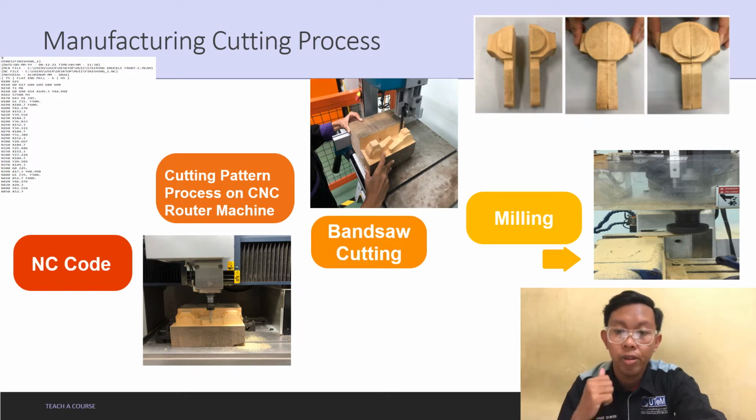Firstly, the advanced machining programming, for which we use the CATIA V5 version, has been created. Two tools are used, which are the end mill diameter 6 and the ball mill diameter 4. With the end mill diameter 6, we use the roughing, facing, and profile contouring processes.